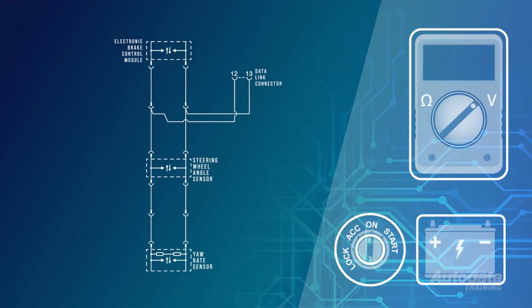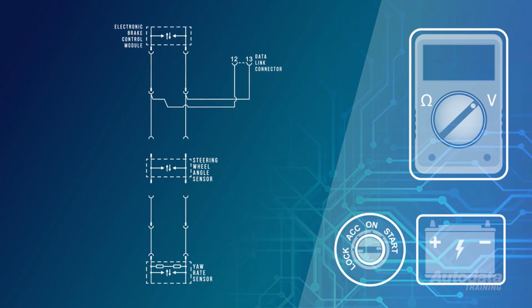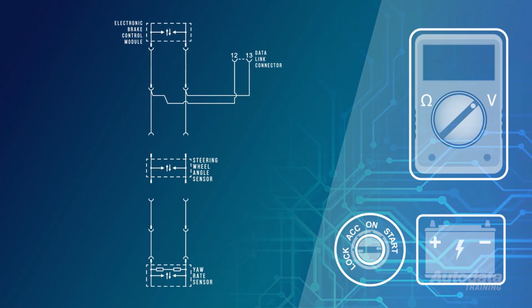As we don't know where the fault is just yet, the best place to start is by looking at the schematic and separating it into two halves. Referring to this vehicle bus layout, the steering angle sensor is in the centre of the network. Turn the ignition off and disconnect the steering angle sensor harness connector. We can now determine which side of the network will require further diagnosis.